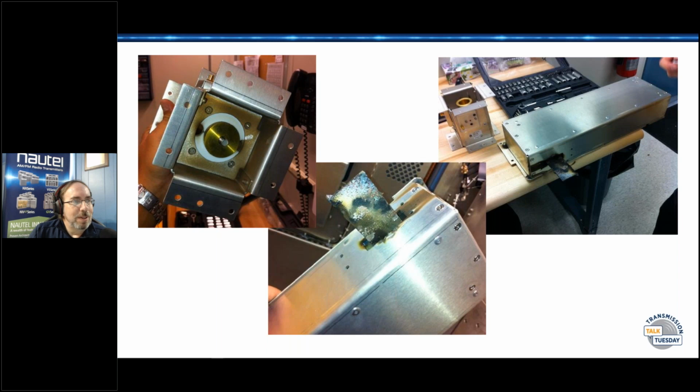Now, I ran into one, and in my particular case, it wasn't somebody leaving parts in. It was a part that had gotten dropped in through the output connector. When we ship these transmitters, there's a plate over the output connection, and on this particular one, you had to take the plate off and install the connector. In the process, they dropped a screw inside the output filter and then put the connector together and bolted it all up, and away they went. And of course, same deal, because it's before the power probe, the transmitter doesn't see it, so it goes till bad stuff happens.